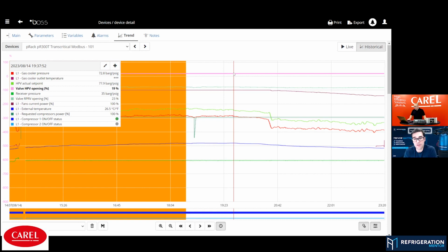Not for a day. If you're running, I've never seen any electronic valve in a process like that where the load changes all the time. Doesn't matter if it's a case valve, you're not going to see the opening percentage just stay there. Maybe a super process plant that is exactly to the T, but any pressure or temperature differential and change will change the percentage of the valve to try to maintain your set point.